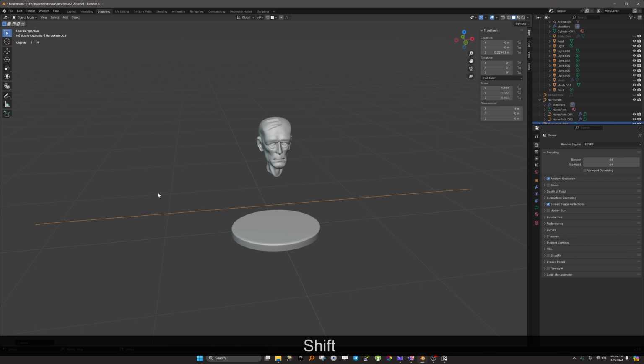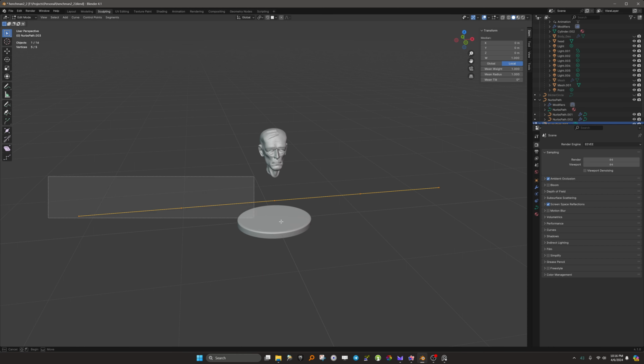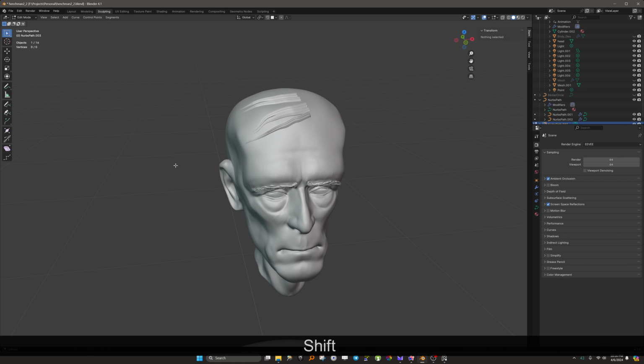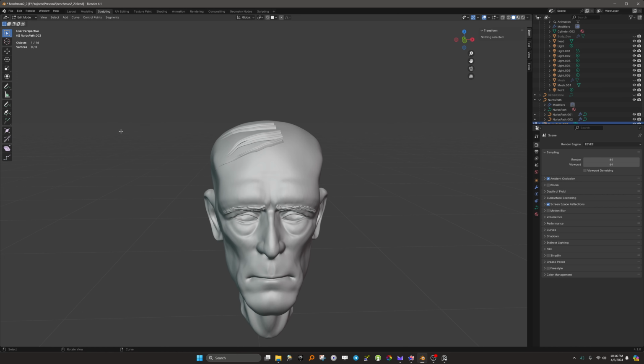Okay, so what you have is a curve, and you go into edit mode, because what you want to do is get rid of these curves. This is what I think is kind of a weird thing about Blender: rather than having a tool where you just draw a path, you have to create a path and delete it. So you go into edit mode, select your vertices, and press delete. And you're like, okay, so now I have nothing. Now what? Well, that's basically just getting rid of all the vertices, but there's still the container for the path.